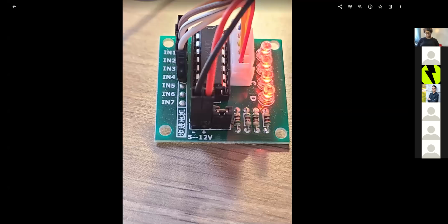Okay. This is how it should be wired, where the black cable is your ground, and that comes into the minus. And then you should have this little jumper placed across these other 2 terminals, and this red wire is your positive 5 volts. Because the diagram in the slideshow doesn't have all these pins, so I just wanted to make that clear.